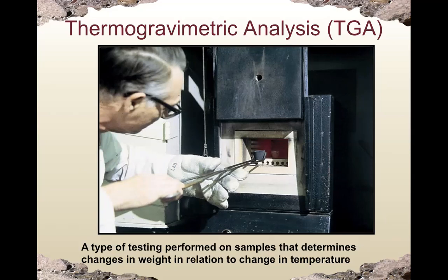If during this test, we found out at 800 degrees, we have a certain amount of weight loss, so that weight loss will be the weight of calcium hydroxide. Okay. So based on this concept, we can somehow study the porosity of the concrete.